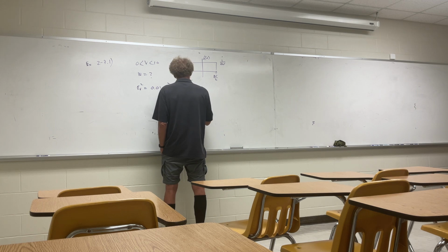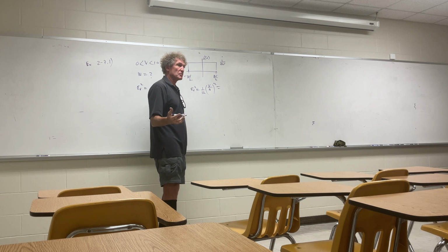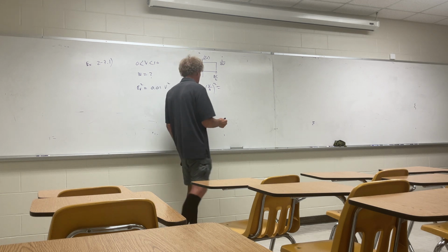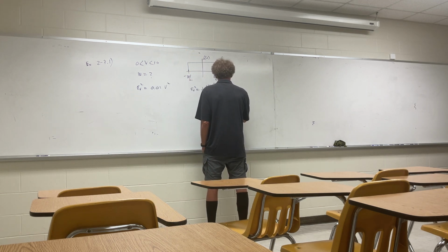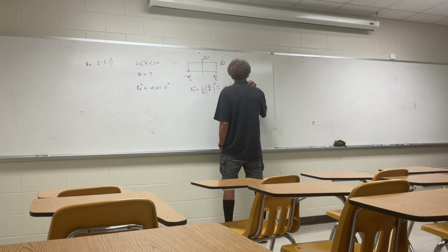And that means for this case, sigma V squared is equal to 1/12 times V divided by N, squared, and that V is the total span, which is going to be 10 volts. So now I can say this is going to be 1 over 12, 10 over N, squared, is equal to sigma V squared. And he said that was equal to 10 to the minus 2, isn't that right?